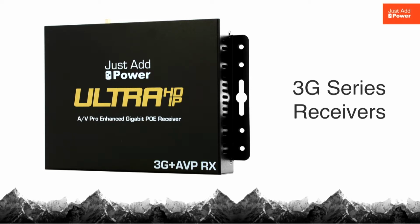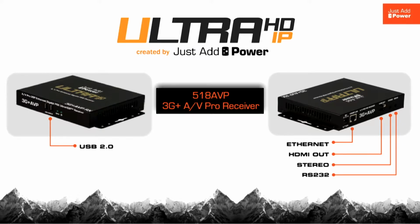So the 3G receivers. We have 2 receivers. The 518 AVP. This has all the bells and whistles on it, USB, CEC capability, and the de-embedding. But if you're looking to do USB control or control devices via CEC, this is the receiver to use. All the receivers have the scaler. The 3G receivers have the scaler for scaling from 4K down to 1080p or 720p. And honestly, the scaling list is extremely extensive. You can scale it to, I believe, even 480p if need be, and some other resolutions for older projectors.